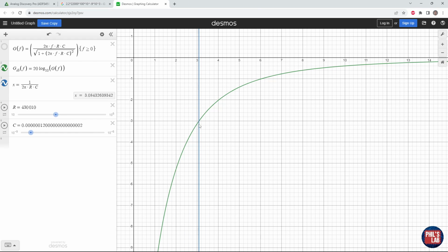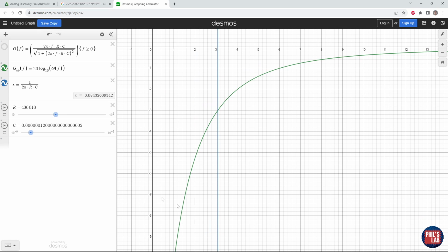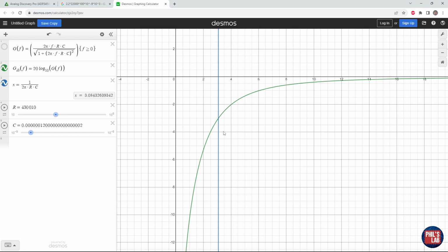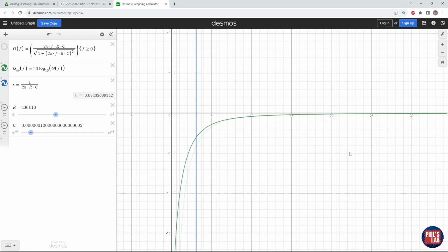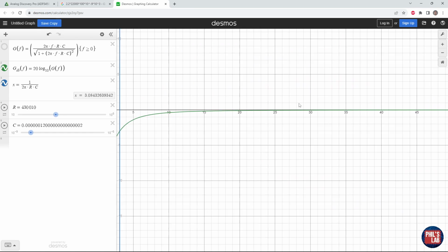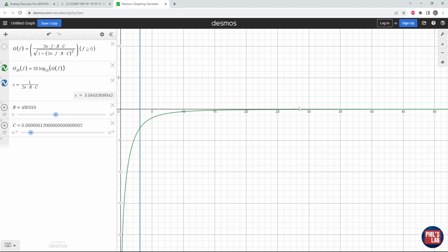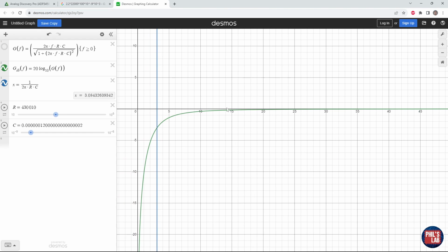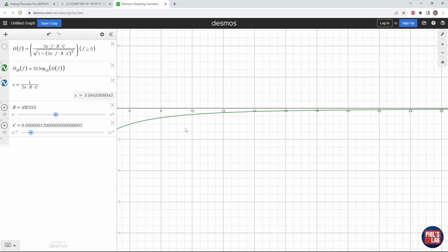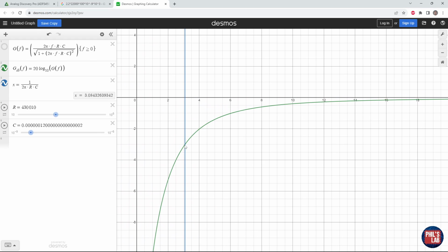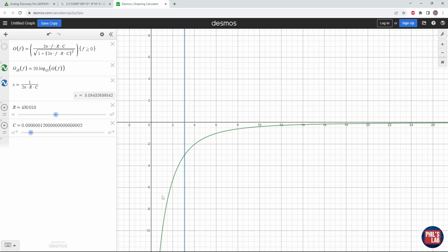So we can say effectively frequencies above the cutoff frequency are passed, and frequencies below the cutoff frequency are attenuated. Now, this is very loosely speaking because actually our passband really only looks like it starts in this certain case, let's say above 25 Hz for this particular filter. Attenuation already starts at around 10 Hz, even though the cutoff frequency is defined far lower. This is something you need to be aware of with these very simple or slow roll-off filters.